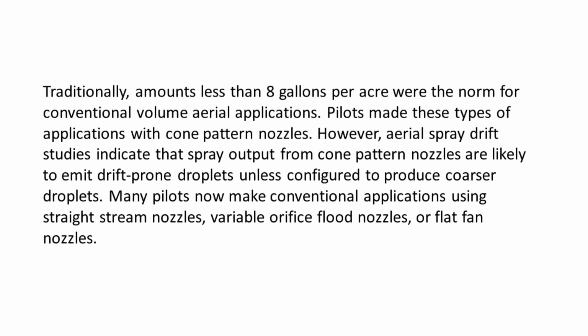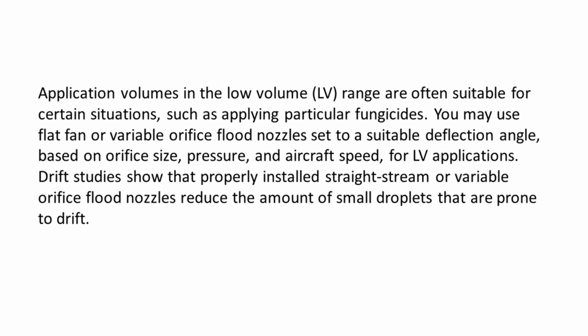However, aerial spray drift studies indicate that spray output from cone pattern nozzles is likely to emit drift-prone droplets until configured to produce coarser droplets. Many pilots now make conventional applications using straight stream nozzles, variable orifice flood nozzles, or flat fan nozzles. Application volumes in the low volume LV range are often suitable for certain situations, such as applying particular fungicides. You may use flat fan or variable orifice flood nozzles set to a suitable deflection angle based on orifice size, pressure, and aircraft speed for LV applications.